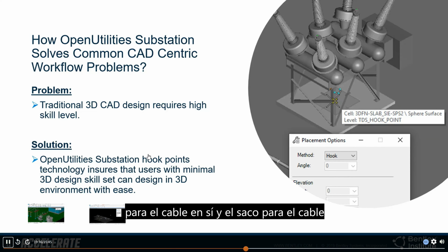So by selecting the correct radius or the level of protection, by selecting either just the lighting masts or a combination of overhead cables and lighting masts or overhead cables only, the rolling sphere is generated based on those parameters, and then users can review if there are areas of the substation that are not properly protected. And there are also some reports that will help us to spot areas that are not properly protected.